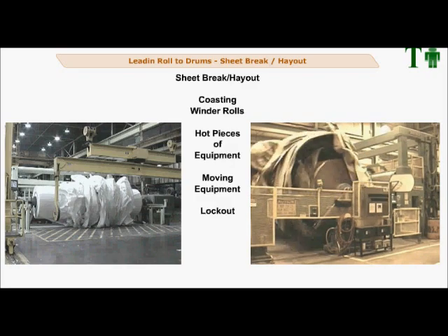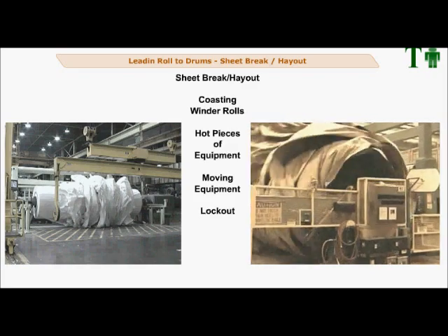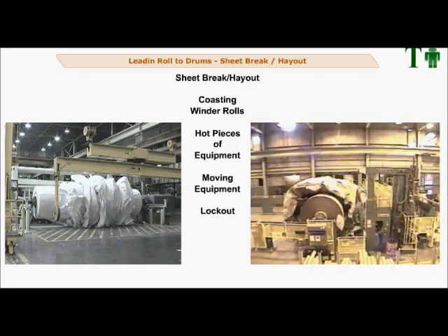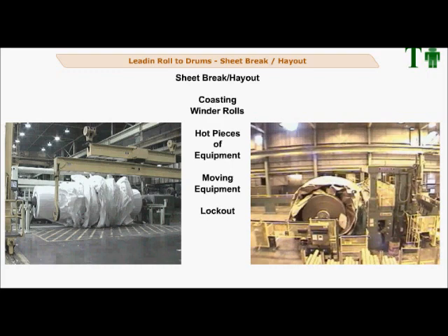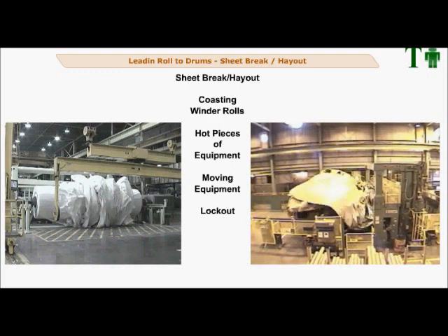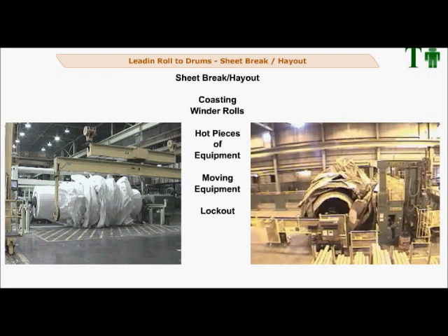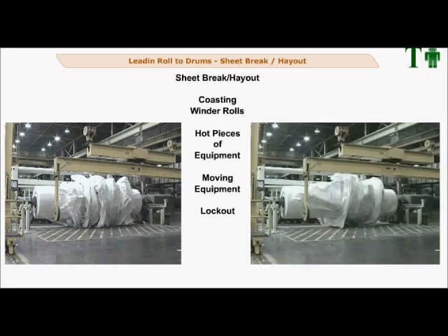The safe distance must be established and communicated at each mill. Paper grades, types, winder speed, number of sets on reel, etc. may cause this to vary. Suggested reasonably safe distances would be never less than 4 feet and generally not greater than 12 feet.